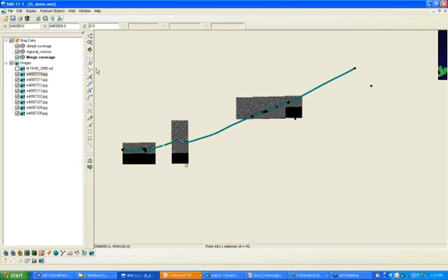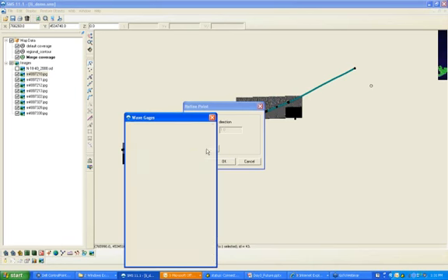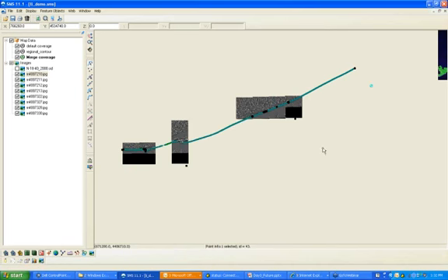All right, and in this case, we have shore normal convention, so we're going to need to set up our grid first. But what I want to do first is actually define the depths of each of these wave gauges. So I'm going to do this by double-clicking, checking this is a wave gauge, going to Options, and defining the depth as 36 meters. I'll click OK, and OK again.